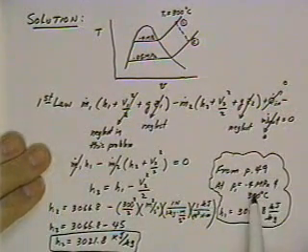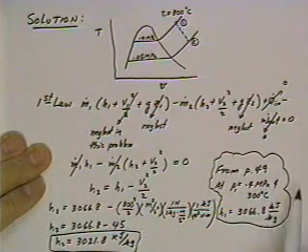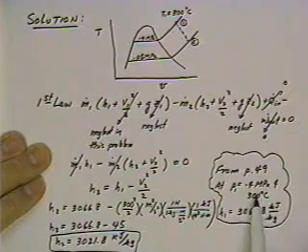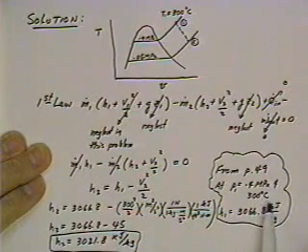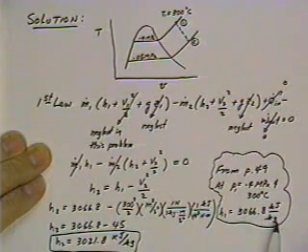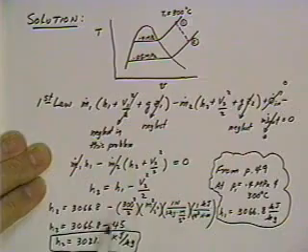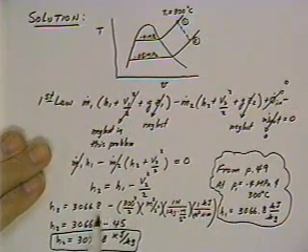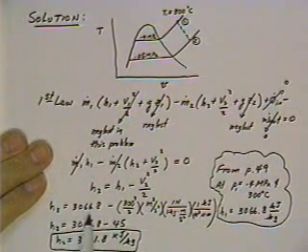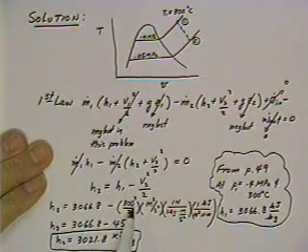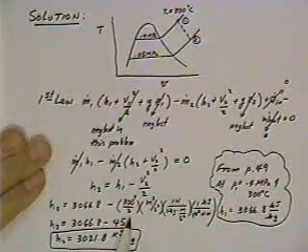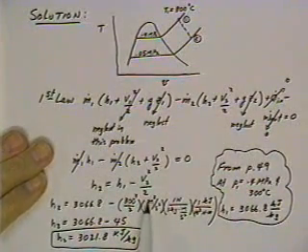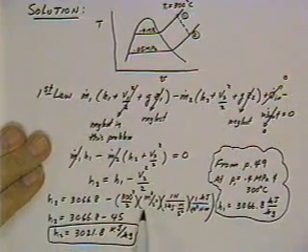Okay, so we just looked up on page 49 from the steam tables at 0.4 of a megapascal and 300 degrees C, we find enthalpy of 1 is 3066.8 kilojoules per kilogram. So we plug this back into our equation, and the enthalpy of 2 is 3066.8 minus 300 squared over 2 is the kinetic energy term. I've filled in all the units here for you.